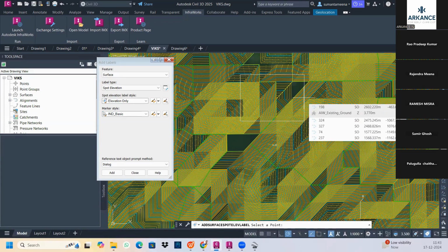If you have your local coordinates based on MSL, then it will take the base as MSL. But if you are extracting from GPS, they are processing the levels using geoid separations, and geoid separation varies from location to location. So I want to ask what reference level this gives. So it means you are saying this is ellipsoid level, and we cannot use ellipsoid level directly for any project.